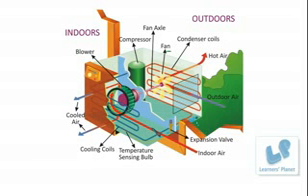It basically turns off the compressor of the air conditioner and not the air conditioner itself. So keep that in mind, that it is the compressor which gets turned off by the thermostat. It senses the temperature at the right setting and then it turns off the compressor, and as the room warms up, the thermostat turns the compressor back on until the room reaches the temperature, right?